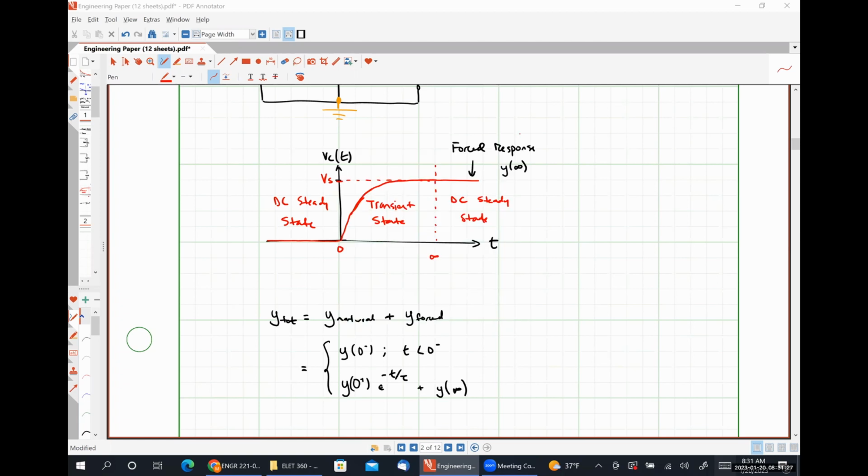Zero. All right. So we're going to have 0 volts where t is less than 0 minus. That's perfectly reasonable. Now let's talk about what our capacitor voltage was at 0 plus. So what was that? At 0 plus, it wasn't Vs, it was still 0 because our capacitor voltage cannot change abruptly, right?